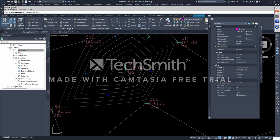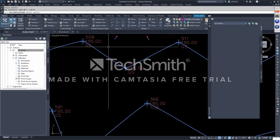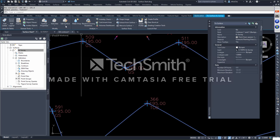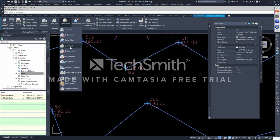I'm still in the command to select a point. I'll reselect it, hit enter, bring it back down to 195. Okay. And then to get out, escape one time. And I should get the ribbon back. There it goes. And you can right click from there. You can right click here and you're going to get the same stuff here. Okay. So edit surface lets you modify, delete, moving actual points, moving this X away from the survey point.